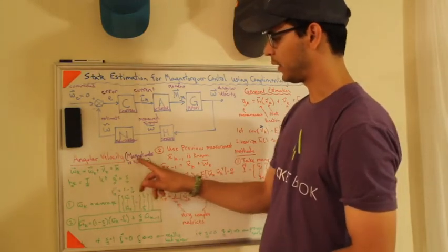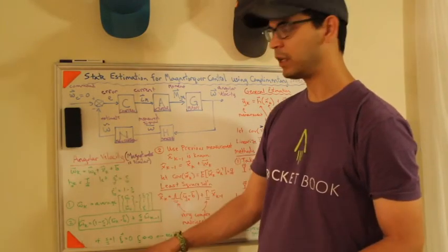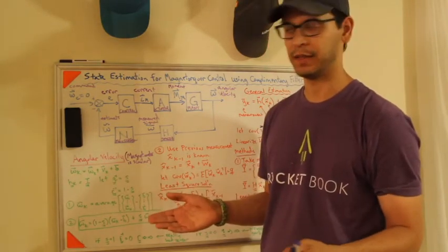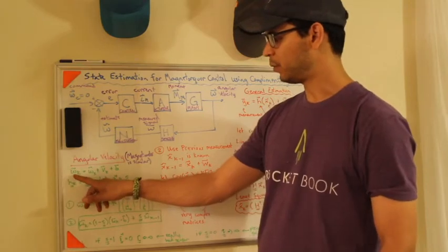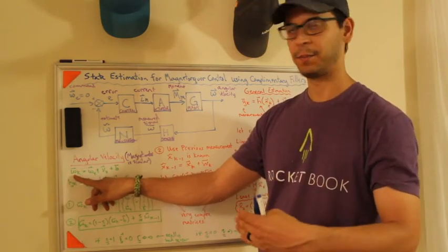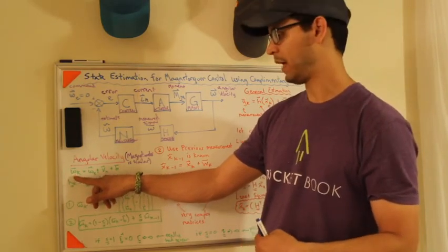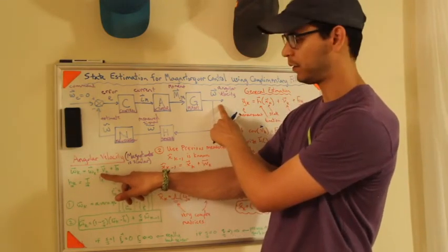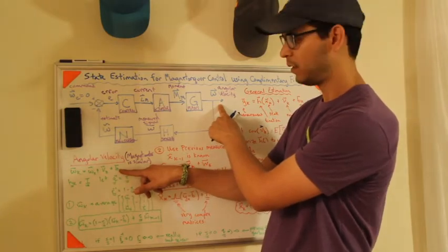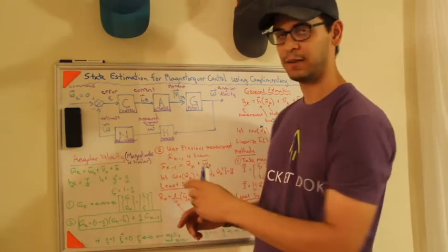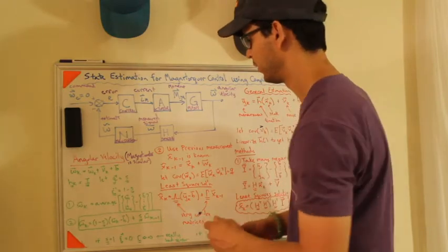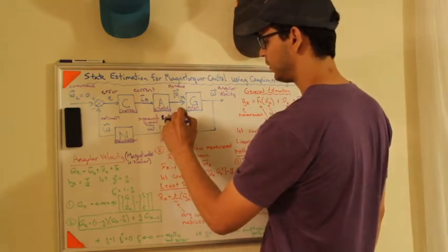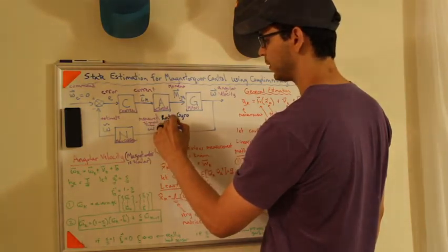So let's dive a little deeper and talk about the angular velocity and magnetometer measurement. I'm only going to do the angular velocity example because the magnetometer example is almost identical. I'm going to assume every kth time step, I get a measurement, and that's equal to the truth signal plus a random noise plus a bias. On a typical spacecraft, you're going to have a rate gyro and a magnetometer.